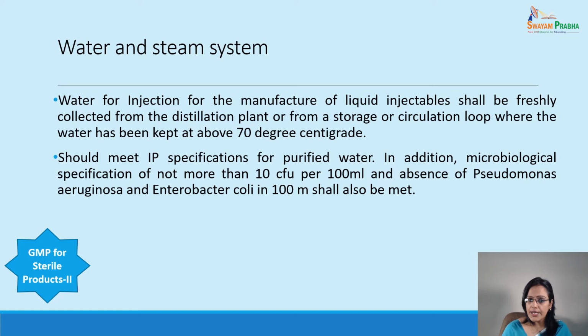Water for non-injectable sterile products like eye drops shall meet the IP specifications for purified water, and in addition, the microbiological specifications of not more than 10 CFU per 100 ml, and absence of Pseudomonas aeruginosa and Enterobacter coli in 100 ml shall also be met.